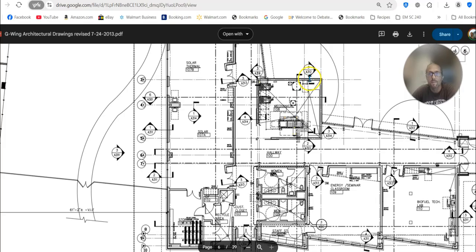It's a side view of the wall, and this has a page number indicated on it, A312, and this is drawing number 3. This is A314 drawing number 3, A312 drawing number 2, and so on. That's the one thing to consider. The second thing that's important is this arrow, see that black arrow pointing to the right? That tells you which direction you'll be facing when you get to that cross section. So we're going to be facing this way, which means to our left will be the outside of the wall, and the right will be inside. Okay, so let's keep that in mind.